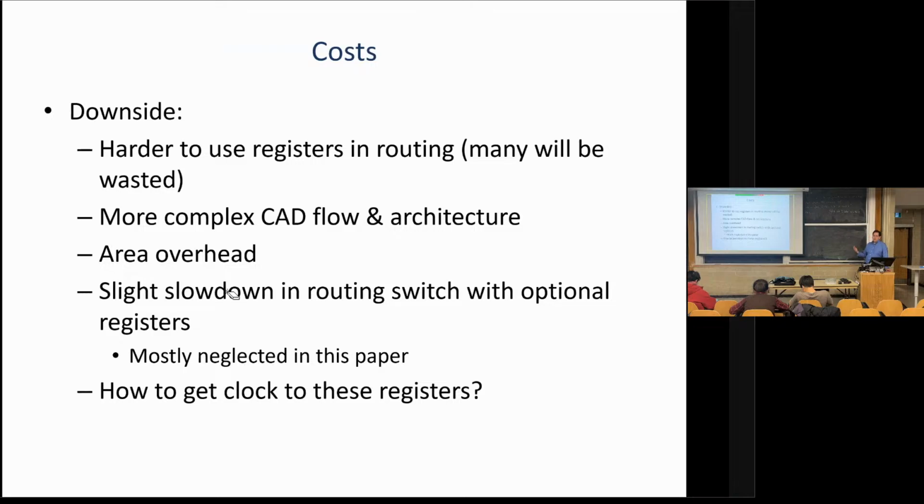In fact, in Quartus, Stratix 10 has an enormous number of registers, okay? So skipping ahead, it's basically got registers at every routing wire. So it's an enormous number of registers. With at least the default CAD options, if your design uses more registers than are in the logic blocks, it won't compile. And the reason it won't compile is Quartus has to first put them in the logic blocks, and then later stages say, this particular register could be moved to the routing and it's beneficial to move it to the routing. So that kind of tells you they're still harder to use for the CAD tool.